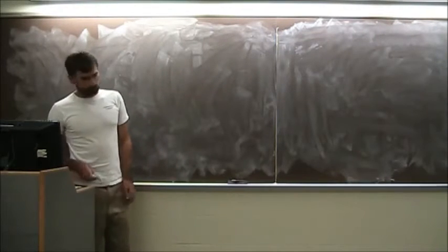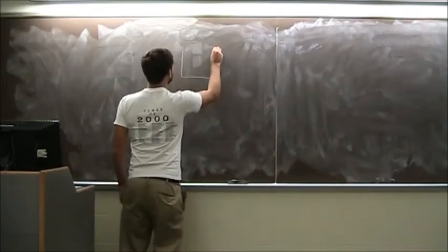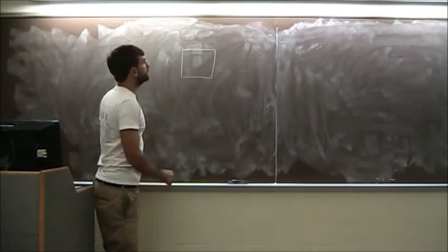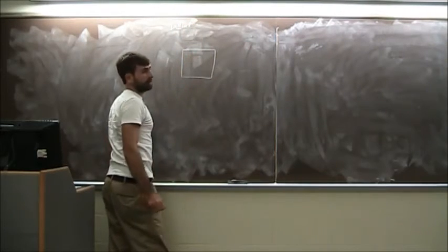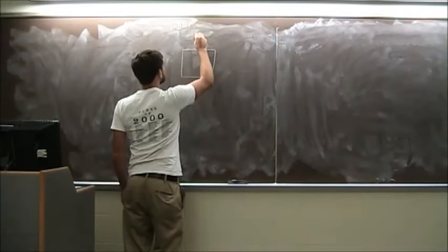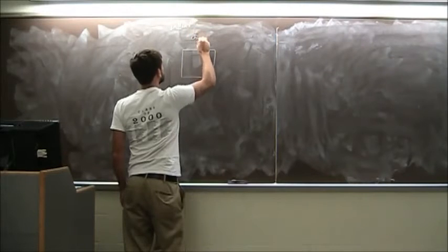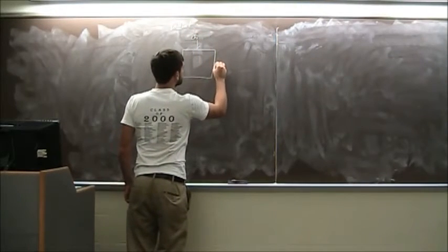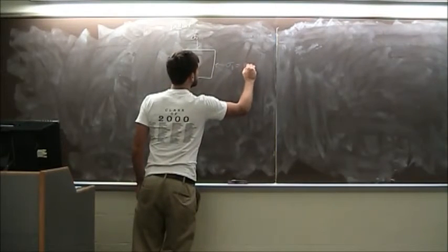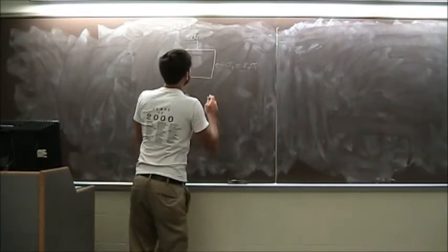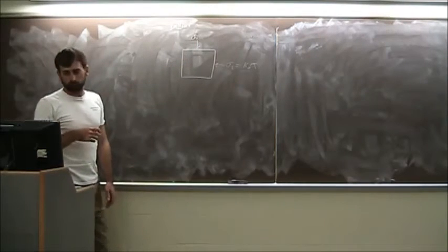So, let's see. I'm going to go back to some soil elements. Just draw a couple here for you. So this is going to be the initial state of what we're seeing. Initially, you have some load, that was that P, which is on top of the sample, and we're just going to call that sigma 1, just for simplicity. And you've got a sigma 3, which is equal to K naught sigma 1, basically the horizontal pressure on that sample.